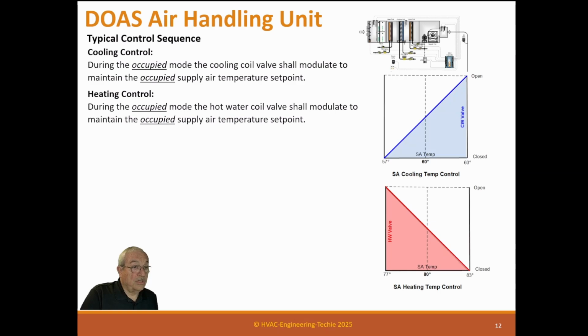To all those units, we can give a little help in air conditioning or in heating. If it's really cold, you can provide 90 degrees to all the air handlers and outside air, which would help them in the heating mode. It depends. Normally we just do 80 degrees to return air, and this may not be 60 degrees. It may be a little warmer, but the reason is a lot of times we have to do dehumidification. But anyway, we'll talk about that in the dehumidification sequence.